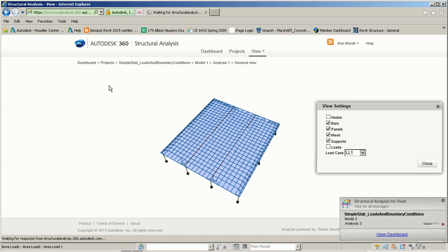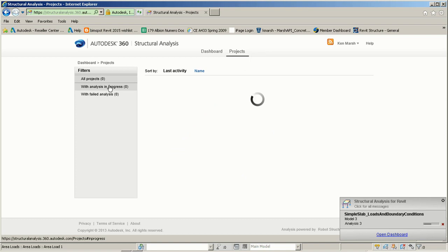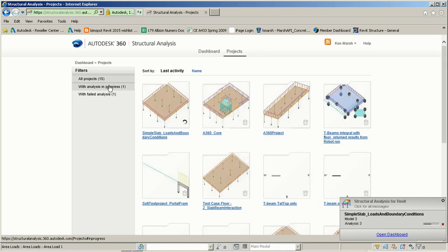Yeah. The question is, is there any control over the meshing or is it just magically done? And the answer is it's just magically done, with the exception that you can set the draft, normal, or fine resolution. So a fine would get you a finer mesh. The draft would get you a less fine, or drafty, kind of mesh. There's no control over actual meshing parameters. You can't add emitters. You can't deal with which meshing algorithm is used. It's just whatever they chose. I'm not sure what it is.